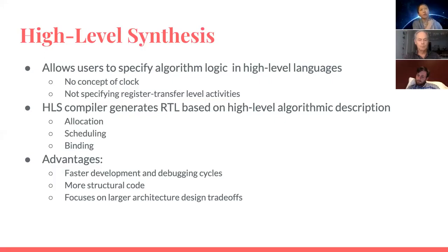Especially the interface connection, which is very standard and should be done in a template way, does not get a good abstraction. A lot of times people spend their time debugging, for example, why loading of this data from the memory to this PE is off by 1 cycle. That's not a very efficient way to design hardware. So what high-level synthesis does is allow users to specify the algorithm logic in a higher level language like C, so that it gets rid of the concept of RTL level signals and clock. We don't have to really worry about the time dimension of the programming, which really simplifies the process of specifying an accelerator.